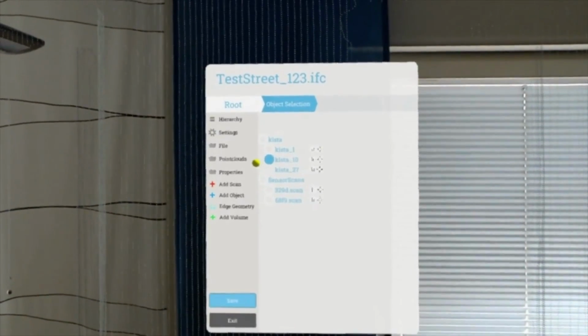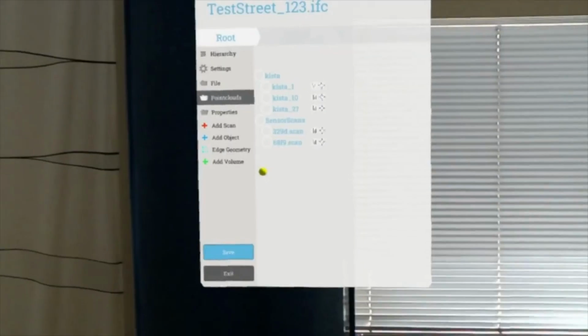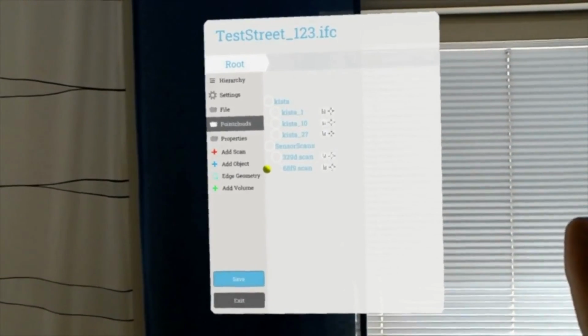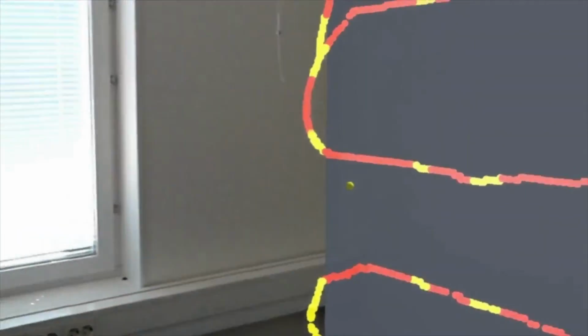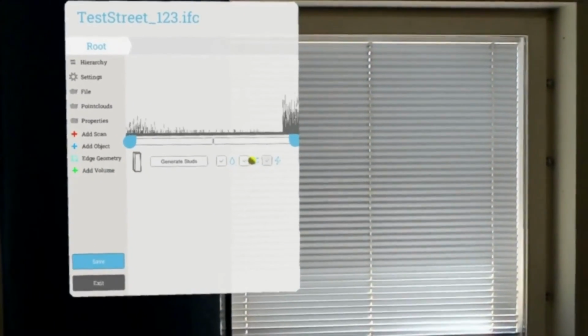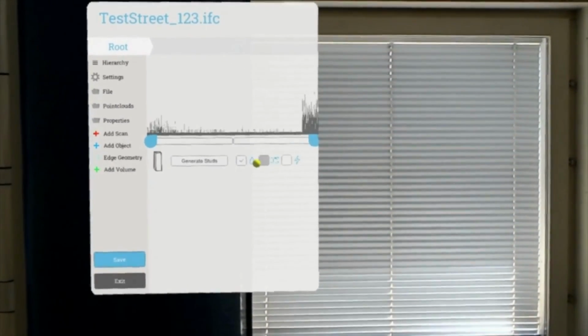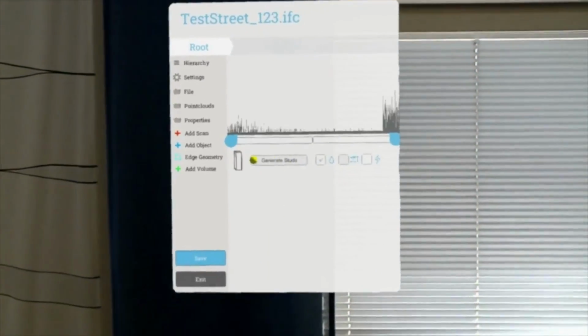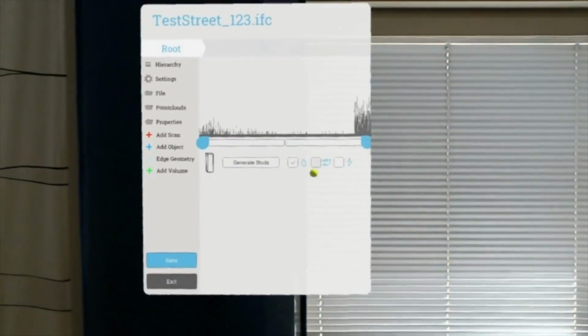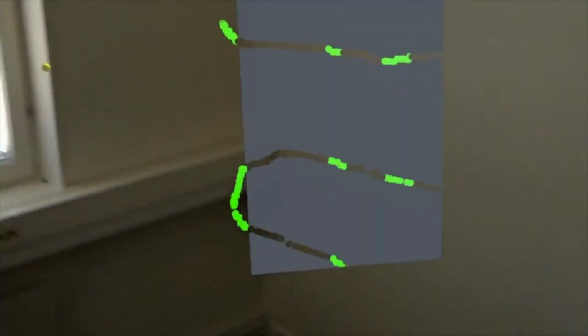That was edge geometry, but we can also generate geometry using a sensor scan cloud. And this is where we come back to the more interesting sensor scan that I hinted at earlier. It works by clustering sensor values at configurable thresholds, which in this case results in beams behind the wall based on the capacitance from the sensor stick.